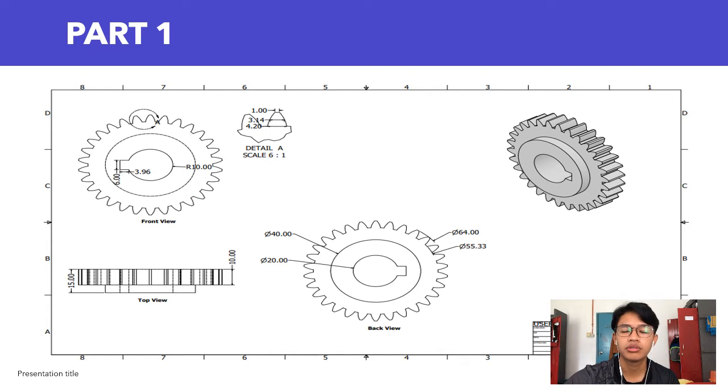The next step is to trim all the lines that aren't needed and set the upper tooth thickness to 1mm. Extrude for 20mm and create a circular pattern with 30 units. Fillet 0.1mm on the dedendum of the circle and create a circular pattern by selecting the fillet on the steps and selecting 30 units of it.